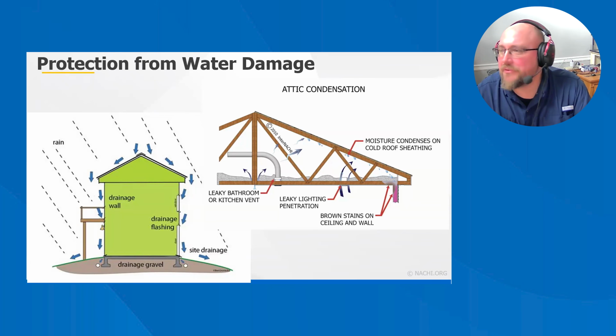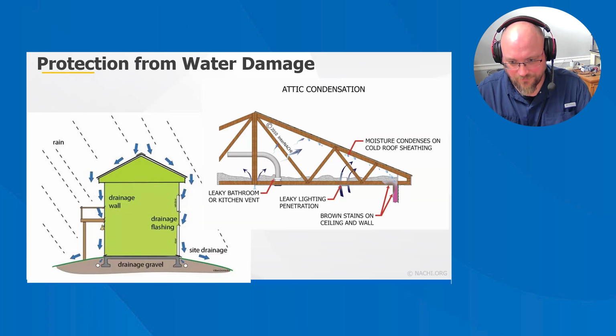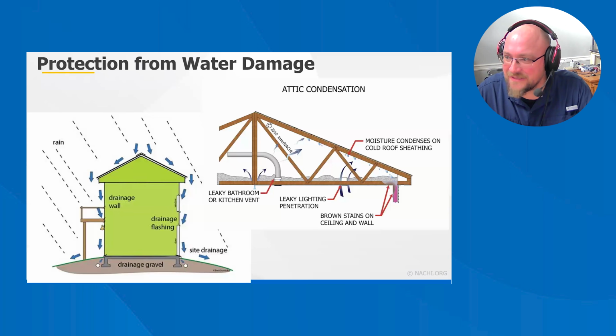So there's a plethora of locations that water can come from. You have windows and doors, the roof, the foundation and exterior walls. Like I said, we're not required to use sill gaskets here, so water or airflow and air carrying moisture with it can easily get into a house. Plumbing, HVAC system, flashings and sealants not correctly applied, bathroom vents, attic vents, ridge vents, humidity, normally damp areas, expansion joints in the brick, interior finish materials, exterior walls, storage areas, that type of stuff.